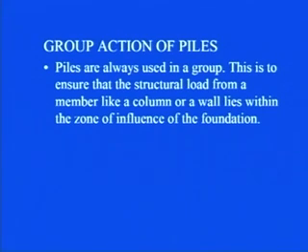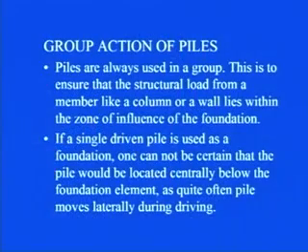So, they are always used in a group. If one single pile is being used, then what are the different problems? You can see here that if a single driven pile is used as a foundation, one cannot be certain that the pile would be located centrally below the foundation element, as quite often the pile moves laterally during driving.